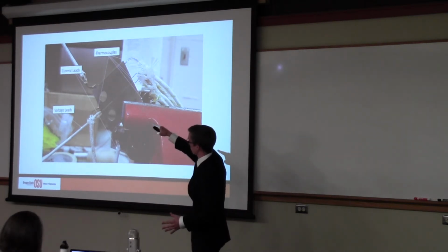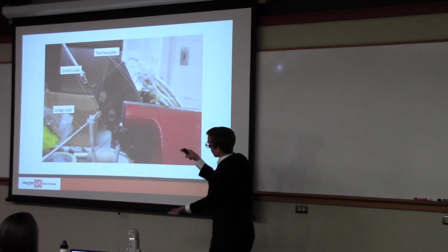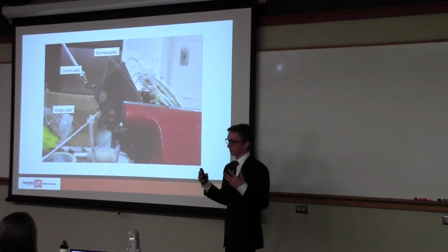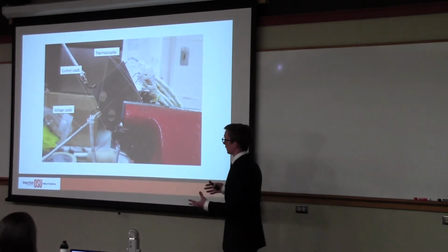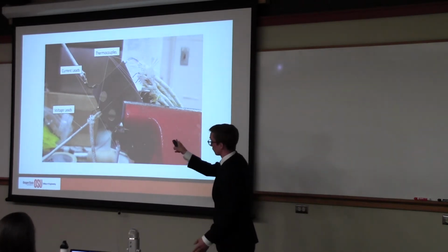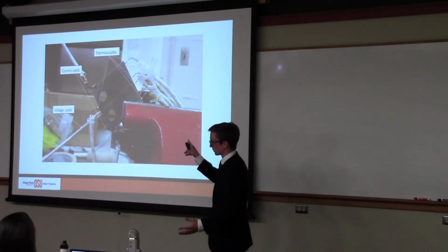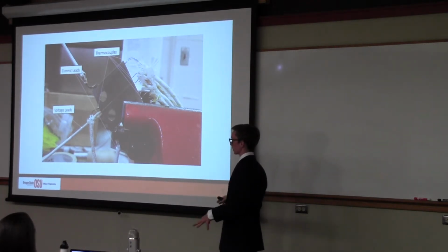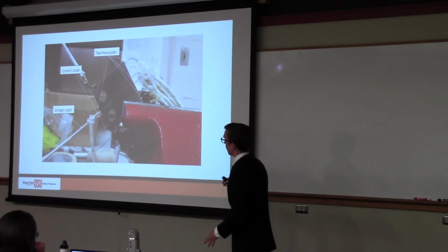is that we're driving current through the sample, and as the crack opens, the current has less of a path to travel through, so the sample's acting as a variable resistor. And so less path to travel through means resistance goes up, and the voltage that we measure across the crack goes up, and then we correlate that to the crack length. So that's how we're actually measuring these things at these high temperatures.